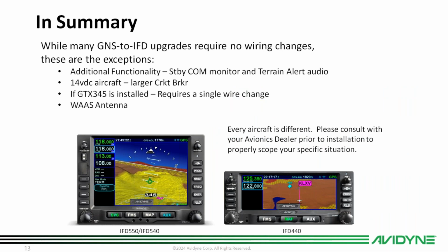So there's a lot of reasons why you could upgrade to an IFD, right? Exceptional functionality. We provide a lot more than what the GNSs originally did. A couple of things we have to remember. We already talked about those special cases, WAAS antennas, things like that, GDL88 we discussed. But also downtime on the aircraft.